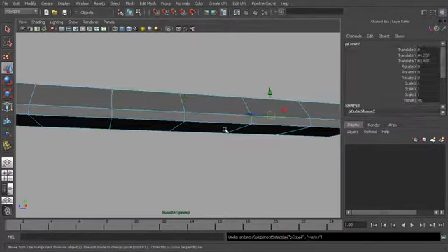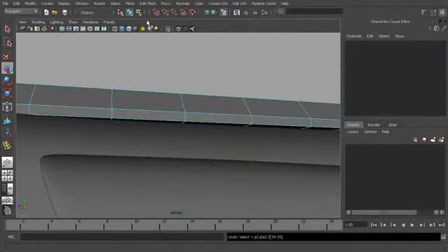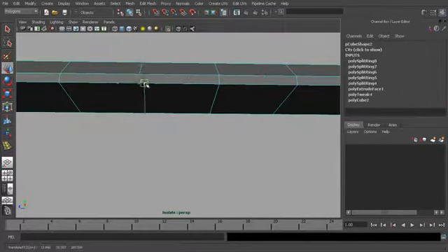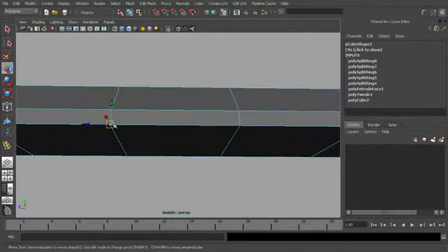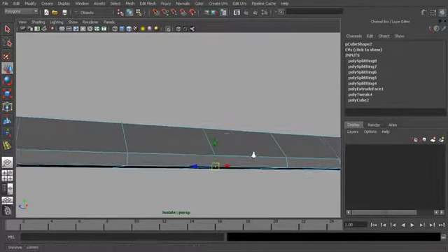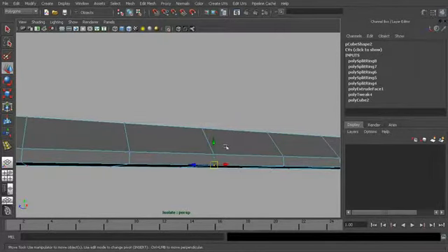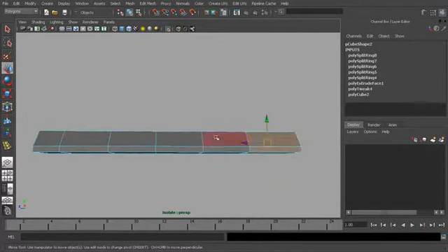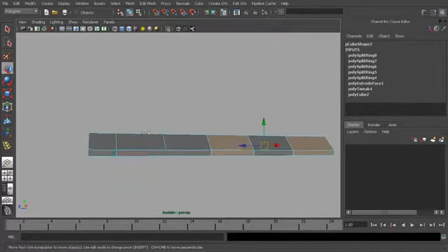Okay, so you can see that because of the undos, there's an issue where we actually had some faces that were extruded, and you could see that based on the fact that I could grab one of those points and pull it off, and it wasn't connected like this. So anytime you're doing an extrude and you undo it, you just want to make sure to go back and check that it's not extruded and just sitting on top of there, because when we do an extrude, it asks us to pull the faces off. If we don't pull those faces off, they're just going to be sitting there, and you're going to come up with some geometry that's not ideal. You're going to have some issues with it. So that was the problem that we were having there with that strangeness.